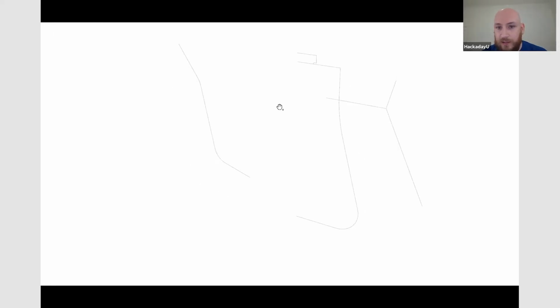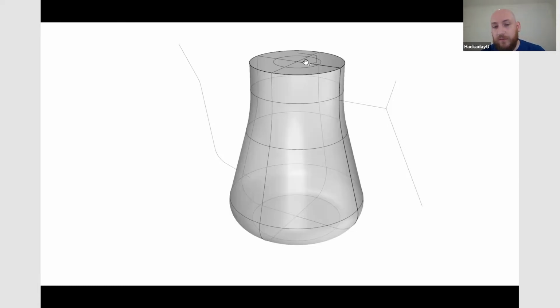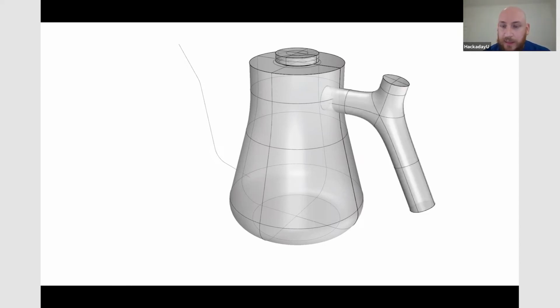Then in perspective view, I'm going to select this edge curve of the main body and use the revolve command, the same as the chess piece, and do a full 360 revolve. Then do the same thing with the top here, which is a thermometer in real life. It doesn't really matter for this. Then I can do my multi-pipe on these 3 different curves here.